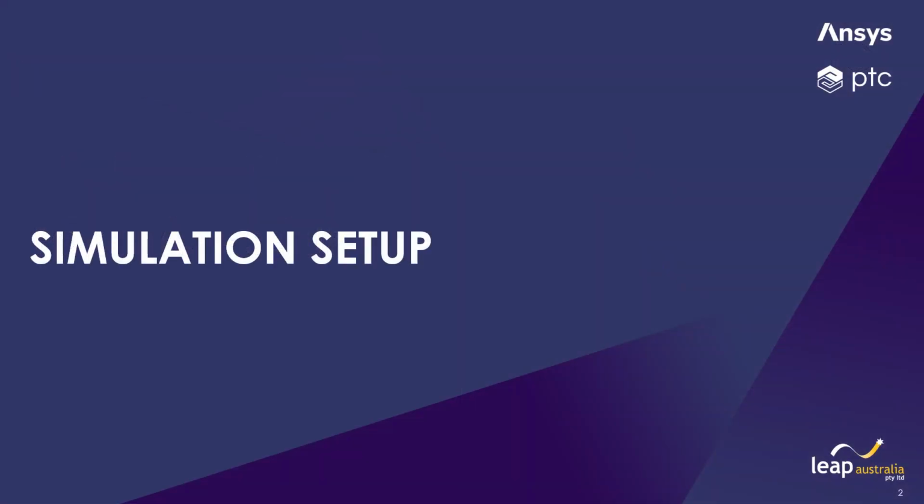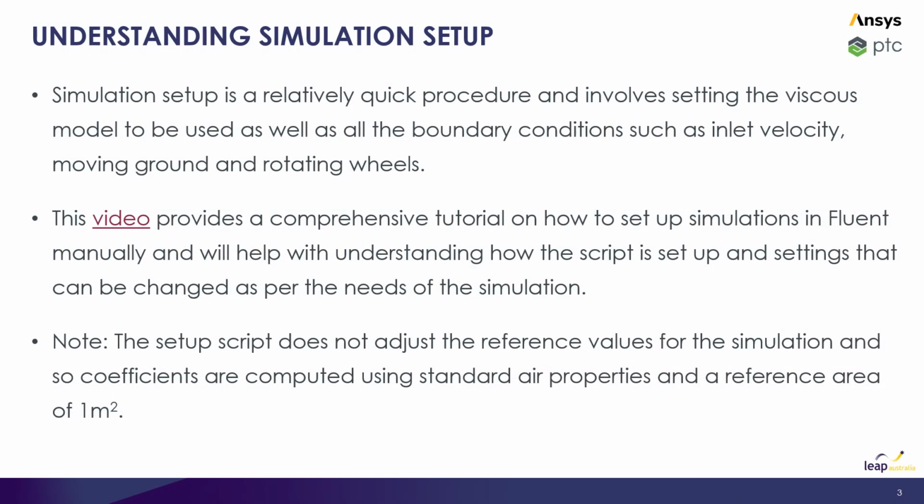With a successful mesh generated, the setup script can now be used to perform the simulation setup prior to running the simulation. Simulation setup is much faster than meshing. It involves specifying the viscous model, simulation type, boundary conditions, moving ground and rotating wheels, output monitors, and run duration.